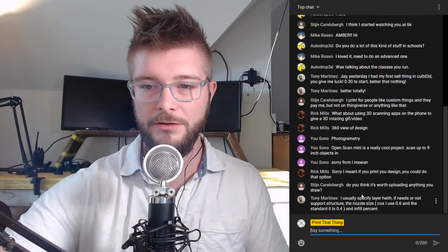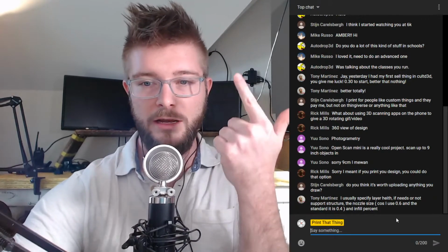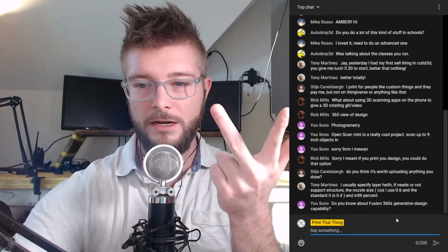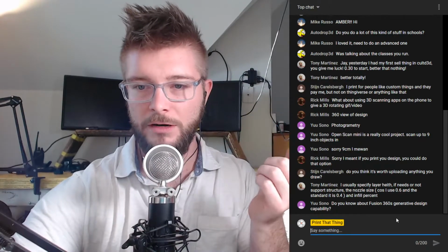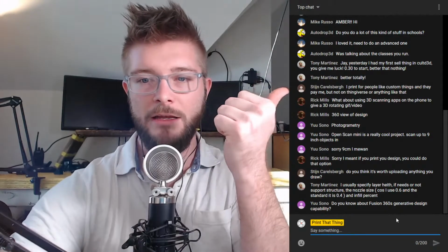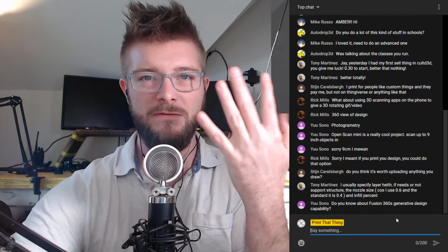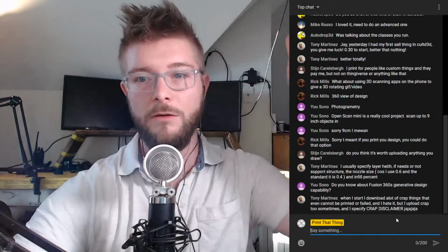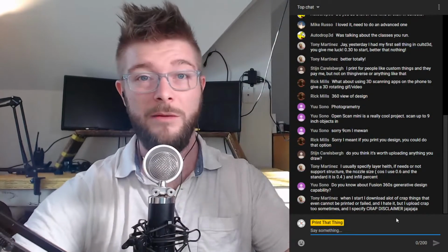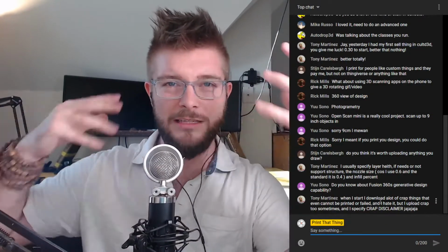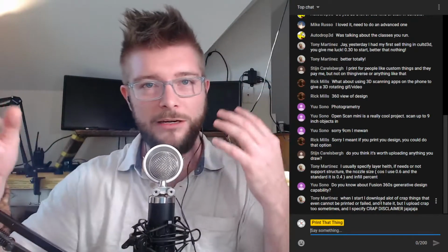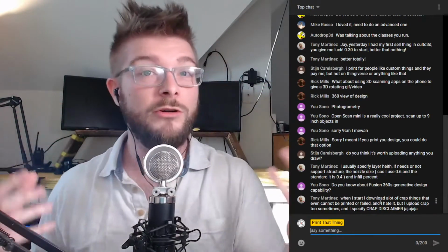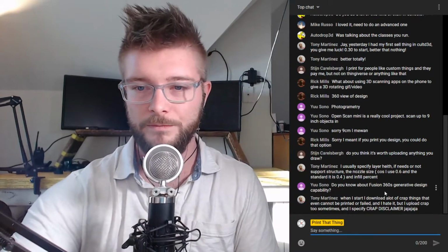Let's see. Tony says, I usually specify layer height, if it needs support structure or doesn't need supports, and the nozzle size, because I use a 0.6. Yeah, I do too, Tony. So Tony uses a bigger nozzle, which I do too, and the standard is 0.4, and the infill percent. So he's doing layer height, support structure, nozzle size, and infill percent. Those are pretty good topics to baseline cover, but if you want to go above and beyond that, you're just going to be above average. I just want to start talking about these things so we can all start thinking, am I being descriptive enough when I upload my designs?